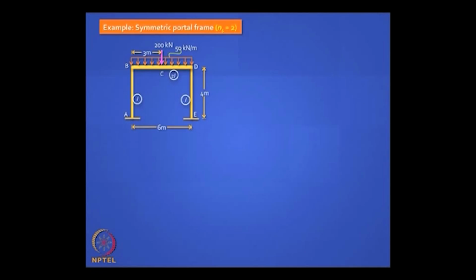So for example, what do you know for sure? Vertical reactions are statically determinate. You should never be thinking of indeterminacy for the vertical reactions. This will be the deflected shape. There is a symmetry in the deflected shape because the structure is symmetric, loading is symmetric. Your vertical reactions are total load.